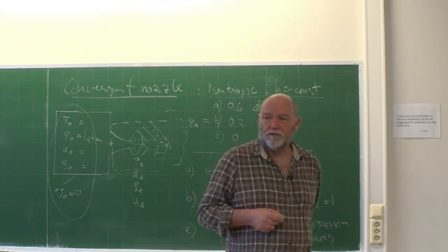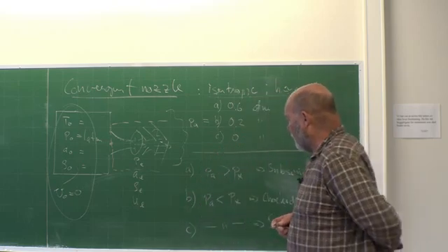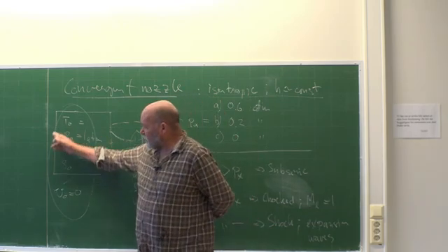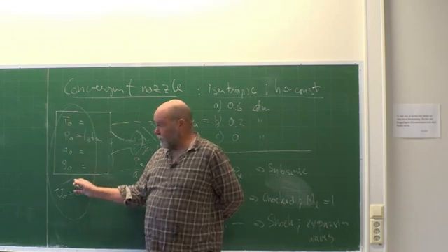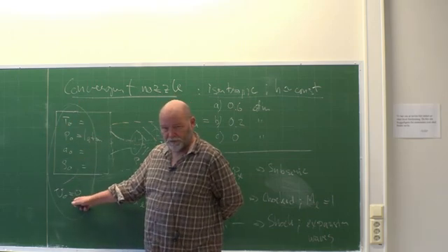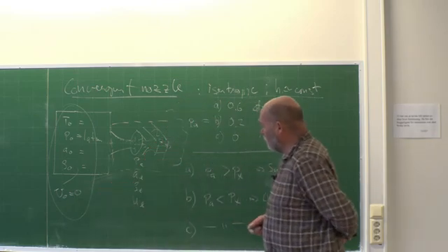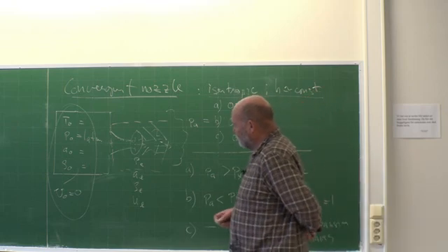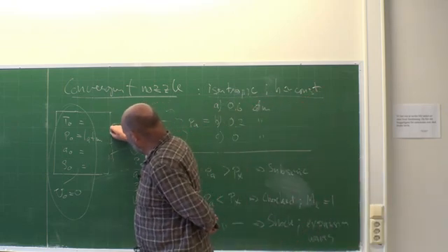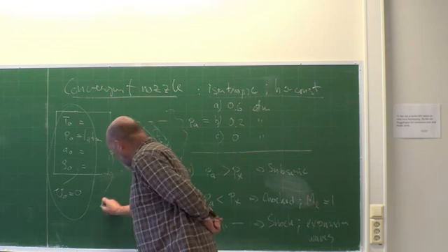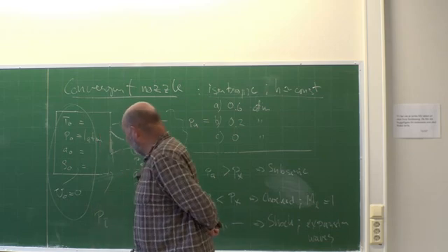Do it easy. So say now you have to put in boundary conditions here. You would like to have the reservoir values, meaning zero velocity. That can't be done. So what are we going to do? Well, we will then here have to invent some, what should we call it? Pressure inlet, something like that.